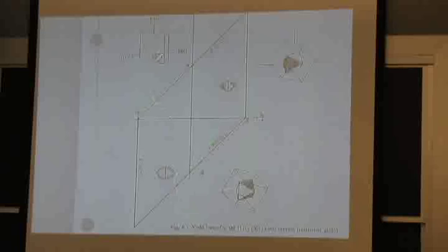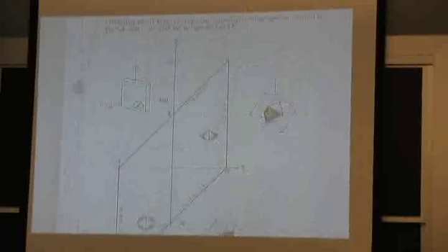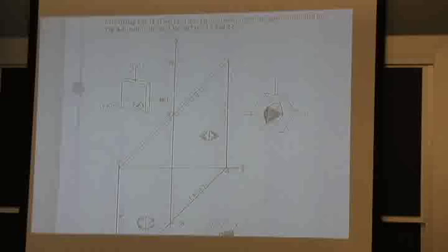Anyway, if I have a cube on edge, not cube on face texture, so I've taken my cube and I've just rocked it up on its edge, and I have this texture, it turns out I still have those same planes here, but with this edge texture, I don't start yielding until double the stress.